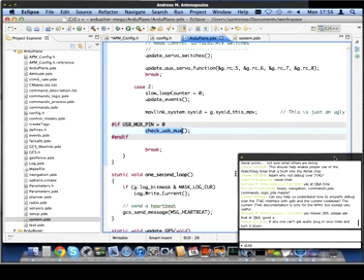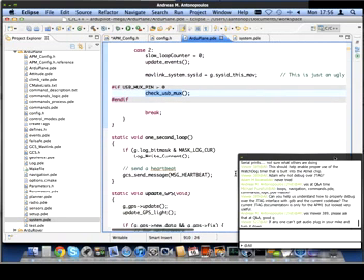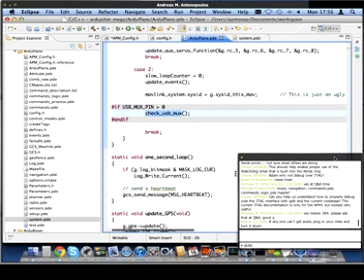And when that pin goes high, it knows that it needs to switch across to the baud rate that you've defined for the radio telemetry link, because it's quite common that people run the USB link at 115 kilobaud, but it's more common to run the radio links at 57 kilobaud. So it needs to check whether you've switched between the two and change the baud rate appropriately.